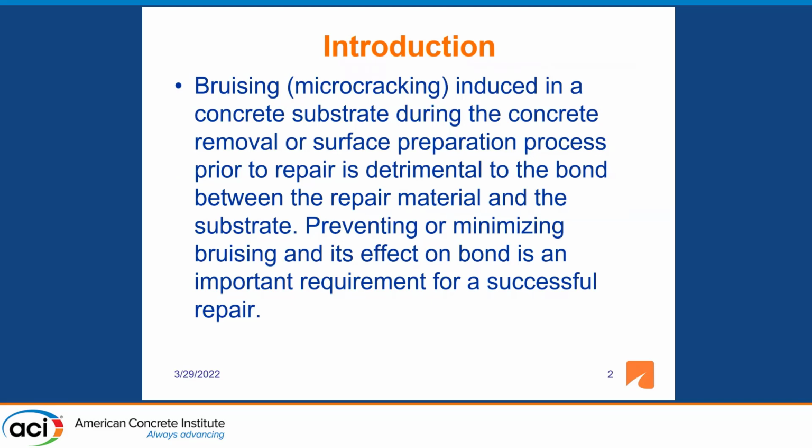Okay, so bruising, microcracking. This happens with concrete substrates during the concrete removal and surface preparation process prior to repair, and it's obviously detrimental to the bond between the repair material and the substrate, because if the substrate's cracked, you've weakened it.